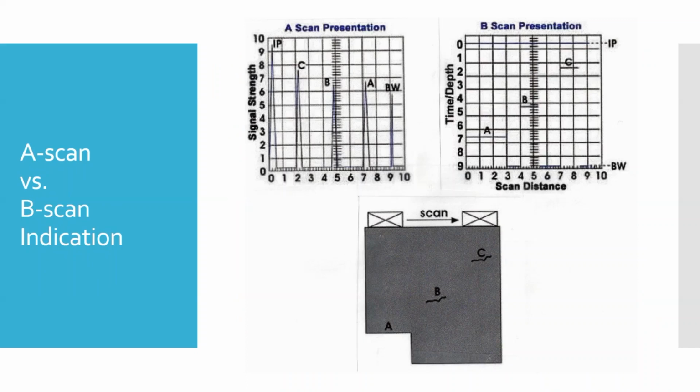So you'll see that with corrosion. When you guys do corrosion, that'll cause a large attenuation of the signal, because you're going off a very rough surface and only a very small amount of the sound actually reflects directly back up again. A lot of the sound gets scattered off in different directions and is never received by the transducer. Okay? So that's an A scan. It gives you the depth, but you can also figure out how wide these cracks are by moving your probe a little bit.